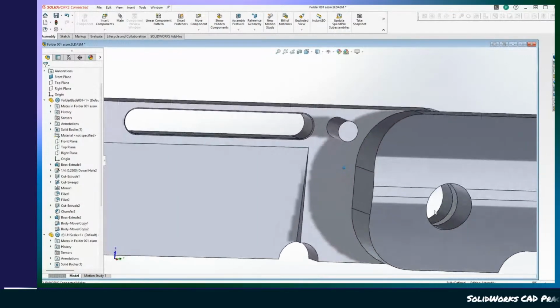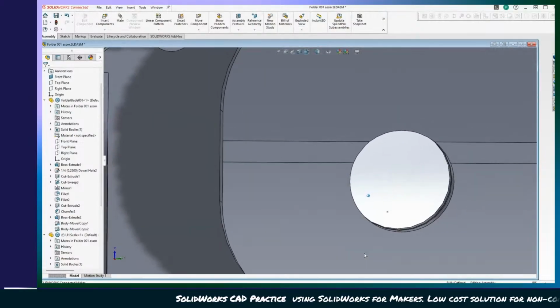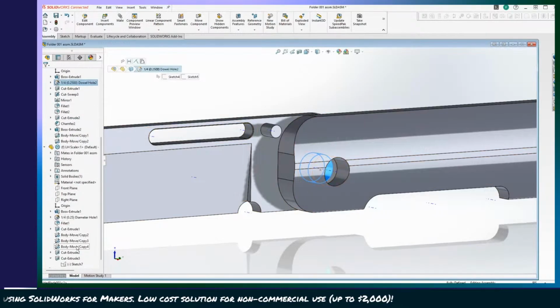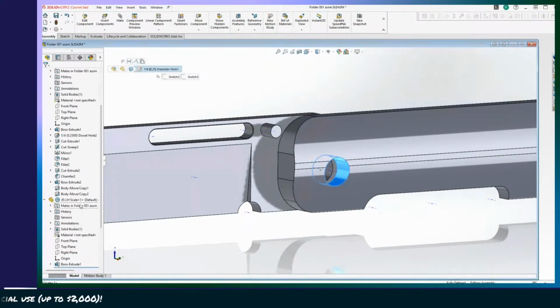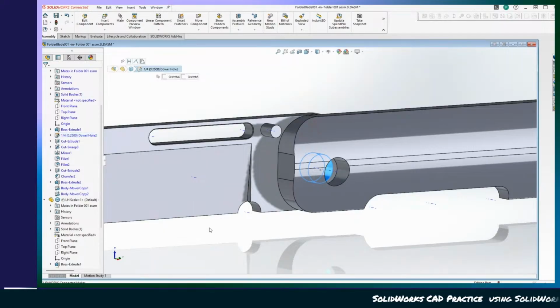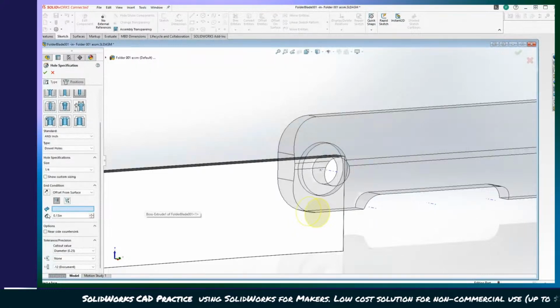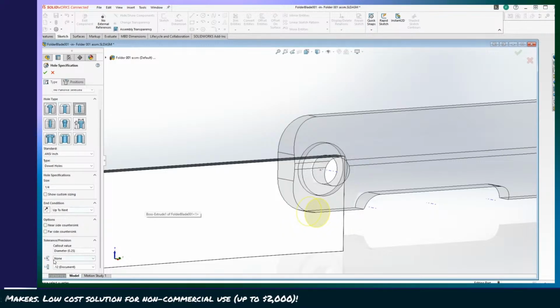So we got the limits on the rotational axis. What did we do here? Those holes aren't the same size, so that's a 1/4 inch dowel hole. And this should be a 1/4 inch hole. Must be some tolerance on that dowel hole. Let's get rid of the tolerance and see if that helps.